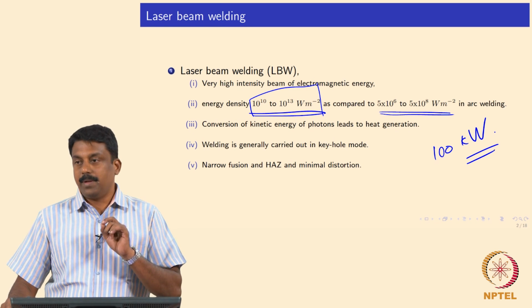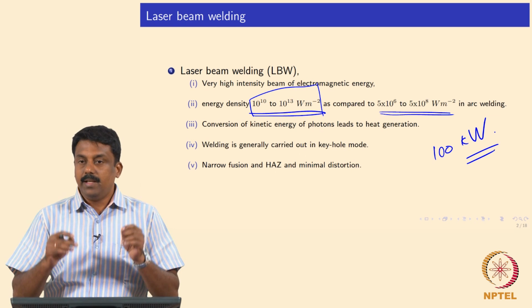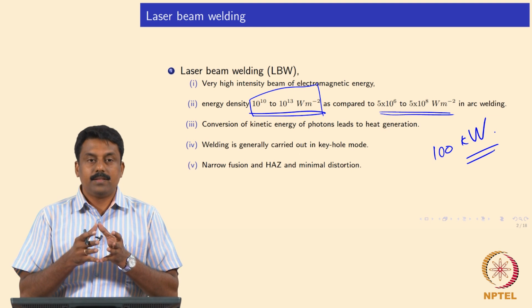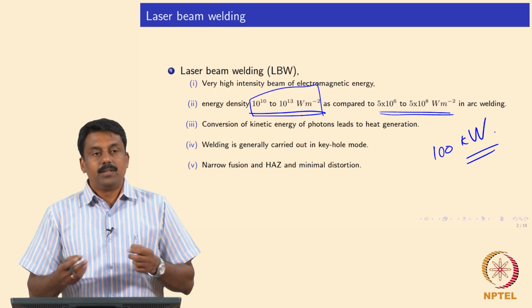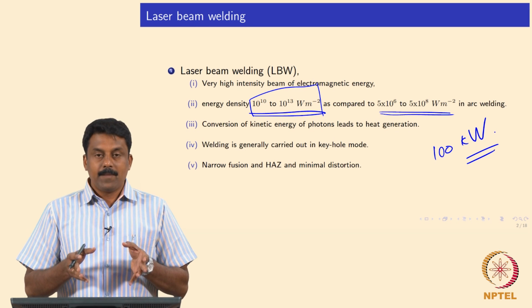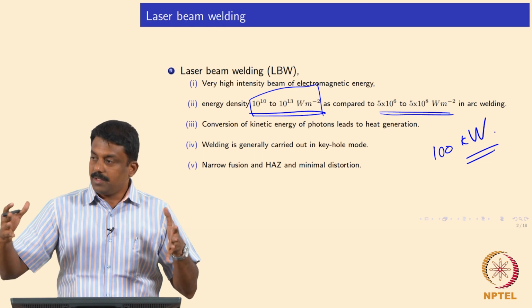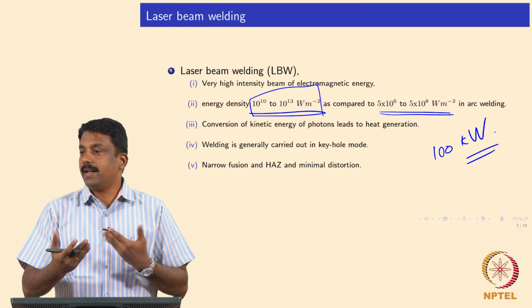Sometimes this is not acceptable. When you have a very narrow weld zone, obviously you also have a very narrow stress concentration area, is it not? The cooling rates of laser welding are much higher, so you may invariably end up getting a martensitic microstructure. So you have a very narrow weld zone in a bulk structure, and that zone is actually the stress riser.